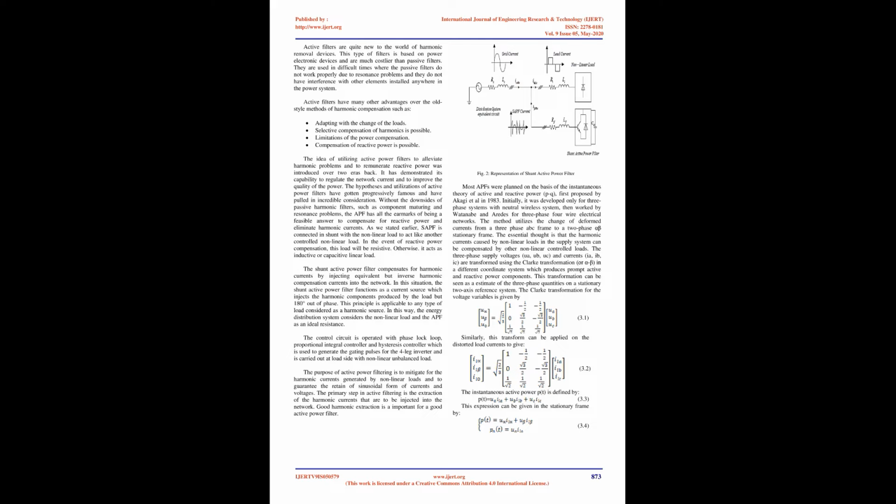Telephones. The most common interference mechanism between power system harmonics and the telephone circuit is induction coupling by the power line magnetic field and the loop formed by the telephone conductor and ground. Conductors. Skin effect and proximity effect are both proportional to the square of frequency and hence increase with increasing harmonics.